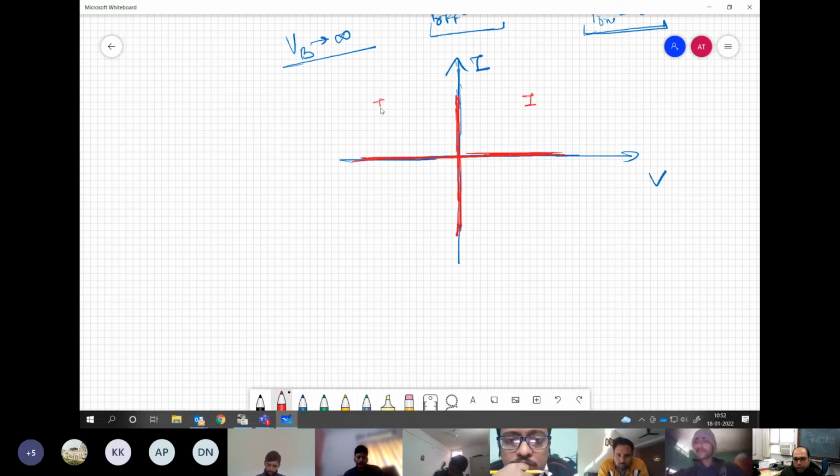So this is basically operating in all four quadrants. These are the four quadrants we talk about. Current may be positive, voltage may be positive, or voltage may go negative while current is positive, both negative, say voltage positive and current negative. These are the four quadrants, possible operations of any switch. An ideal switch operates in all four quadrants.